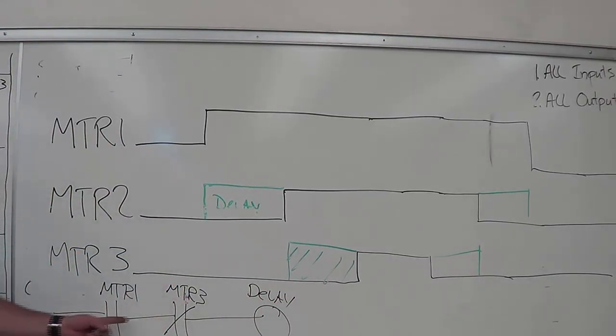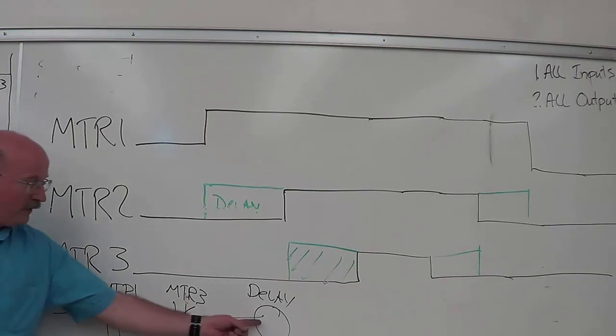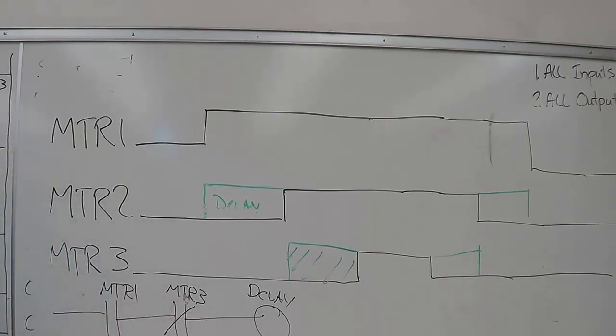If motor 1 is on, motor 3 is off, that must mean we're in a delay period. We're using motor 3 as like motor 6, right? I'm just using an example instead of putting all 6 motors up here. Right, yes, motor 3 being the last one. And so motor 1 is on, and the last one here is motor 3, so I put that here. So the first one to shut off is going to be motor 3. Those contacts will close. Motor 1 will still be on, right? And so that tells us we're in a delay period.